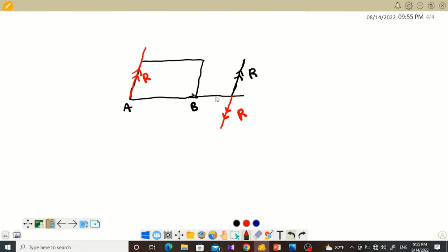So as you can see now, our first initial resultant is cancelled, and a new resultant force is acting through the point A. And in the system, we have added a couple. This is the couple; I circled it.